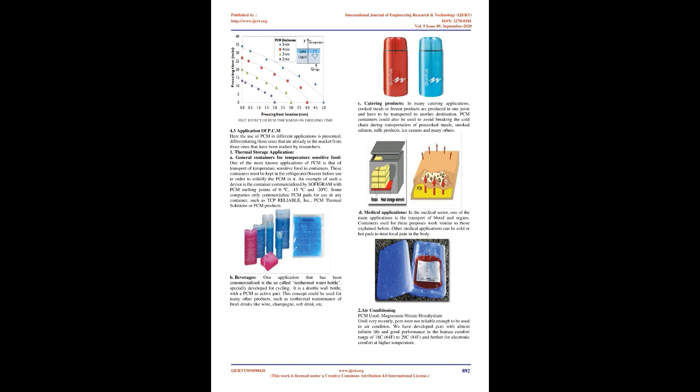The PCM total storage capacity varied between 138 kJ for a 2 mm slab and 345 kJ for a 5 mm slab. The heat load and cooling capacity used to predict the PCM melting and freezing times with different thicknesses correspond to an ambient temperature of 25 degrees Celsius, and the model results are shown in figures below. Effect of PCM thickness on melting time.